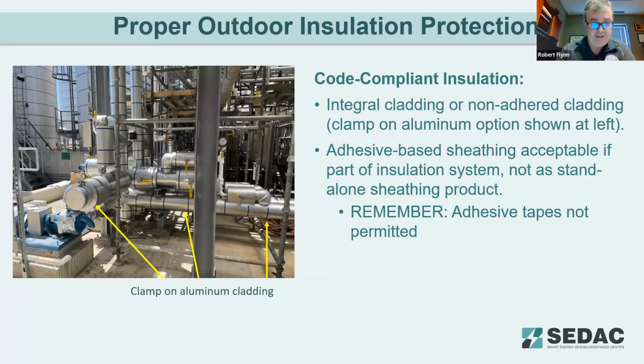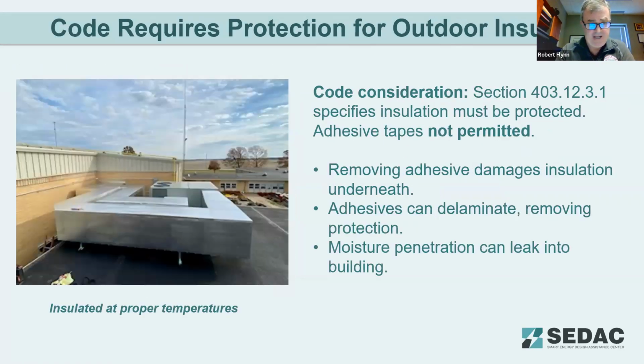Sean, one more thing before we go to this next slide here. If you look at the last picture, the insulation looks really good, really nice job, really tight job. However, many times in specs you'll see they're actually asking for a watershed, whether it be at the center, a higher level at the center of the ductwork, or on one side or the other. Have some type of pitch on the top of the ductwork where you actually see the watershed, where the water will actually not end up becoming a part.